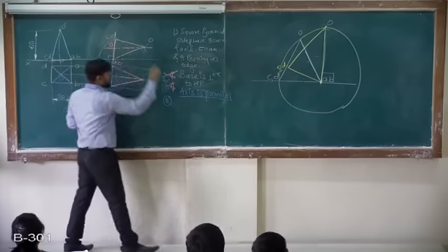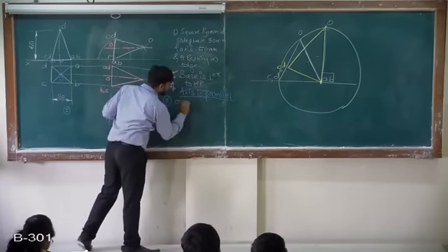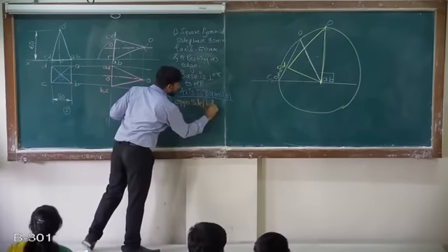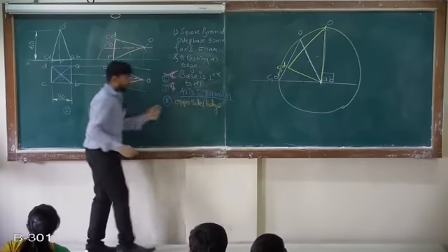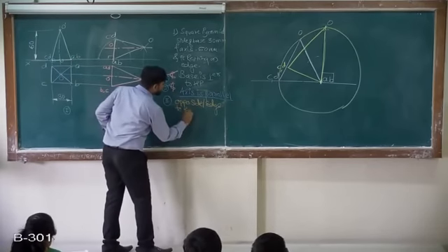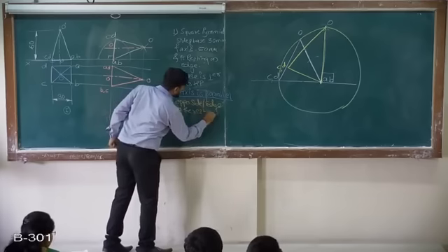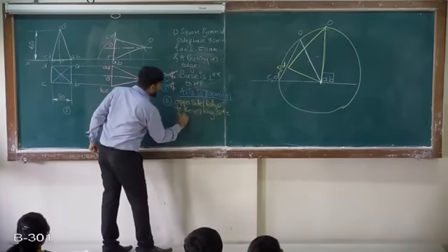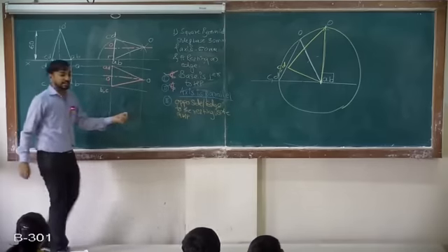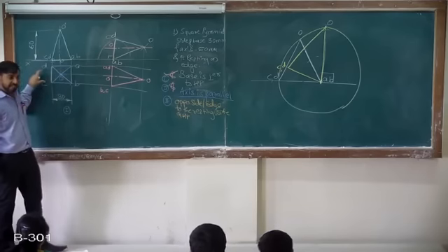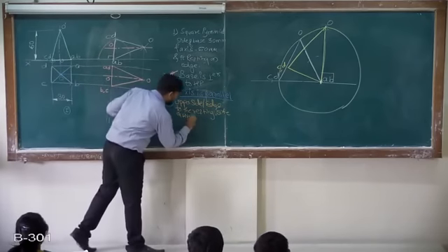So I can say opposite side or edge to the resting edge or resting side on HP. So resting side on HP is AB. Its opposite side is CD. Is at maximum.